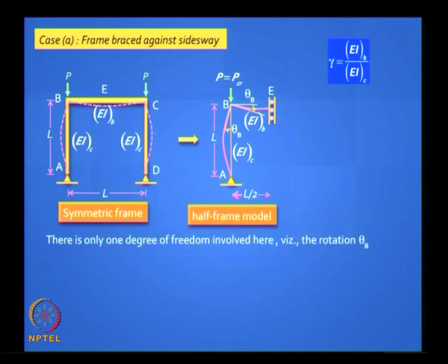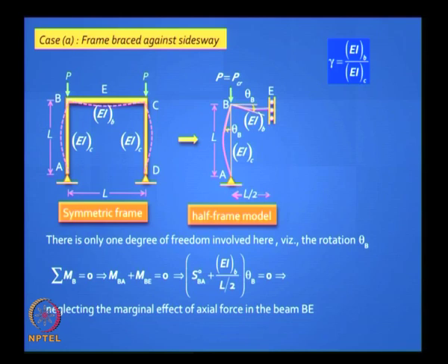Theta B, okay, 1. Write down your equation. Okay. Now, we make an assumption here: we are saying that we worry about axial compression only in element AB, we do not worry about it in BC, because if you worry about it in BC then it is a more complicated problem. Why do we not worry about it in BC? Because it is going to be very small.